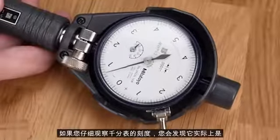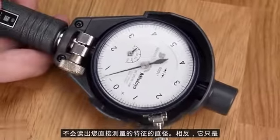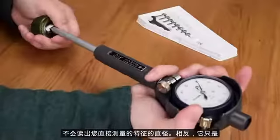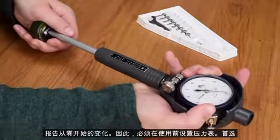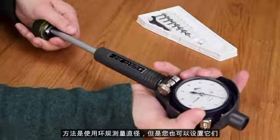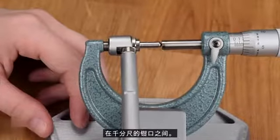If you look closely at the scale of a dial bore gauge, you'll see that it actually does not read out the diameter of the feature you're measuring directly. Instead, it reports a variation from 0. Hence, the gauge must be set before use. The preferred approach is to use a ring gauge for the diameter being measured, but you can also set them between the jaws of a micrometer.